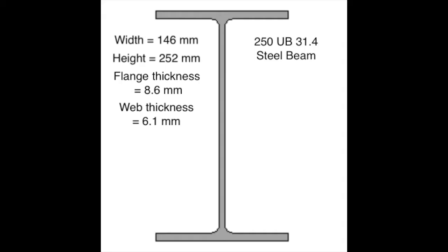The design challenges faced were that the beam was located on the outermost edge and was required to hold greater loads. This meant it had to have a larger cross-section and required a greater ability to withstand shear stress. Following research and calculations, the cross-section of the I-beam was chosen as follows in the image.